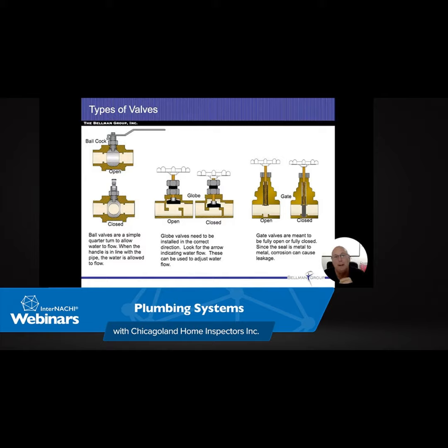This was in that same house that we saw the mechanical trap. Obviously, they've updated some of the plumbing, so you can see the cast iron going out to the street, and then we have a PVC pipe going up and to the left on there. They also had a building trap that I thought was interesting. Typically, we don't see that.